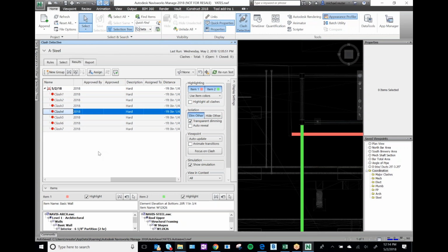You're going through these looking at them one by one. Put that 2-second animation over, let's say, 600 clashes. You do that 600 times, that's 10, 20 minutes that you wasted. So it adds up quick. I recommend not having that on.